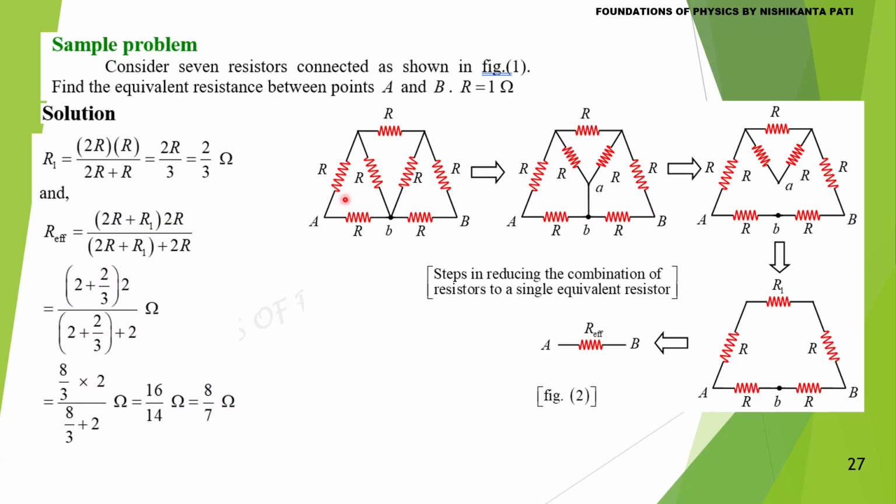The given circuit is equivalent to this. We know from the previous problem, if a battery is connected between A and B, no current will flow in this wire. It is now a connecting wire. It may be a resistor also. So this AB joining part we can remove without affecting the current distribution. Hence the given circuit is equivalent to this.